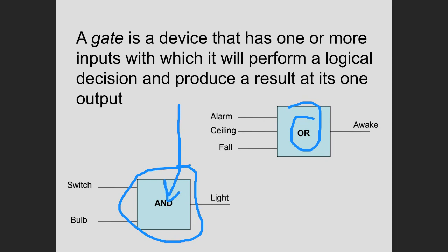So we really don't wire switches in series. I mean, they used to. When you did your PLC history assignment, the first homework, they used to use not so much switches, but relay contacts in series or parallel to implement logic. But now we can do it in solid state. And remember, solid state means no moving parts. We can do it with these little special switches called transistors.